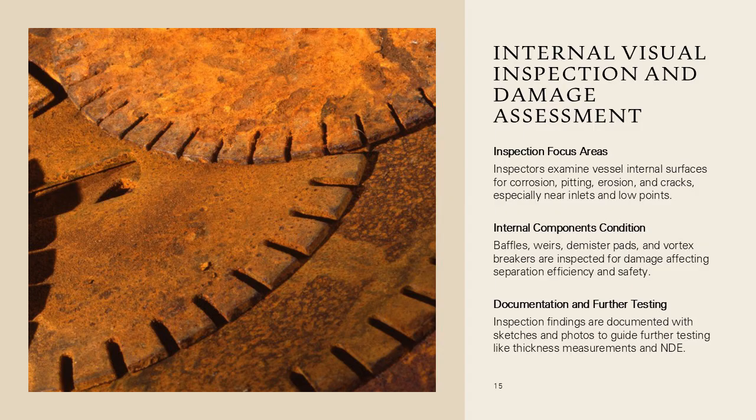impact the pressure boundary. Findings from internal visual inspection form the basis for further examination, such as targeted thickness measurements or surface NDE. Clear documentation of observed damage, including sketches and photographs, is essential for accurate assessment and future comparison.